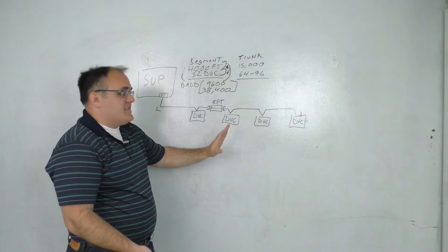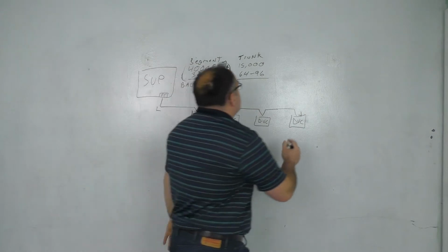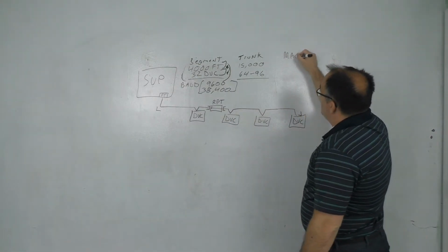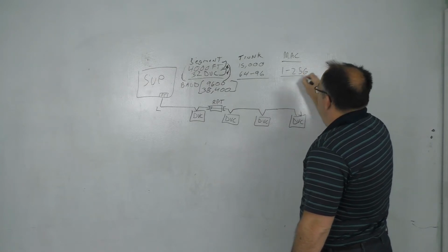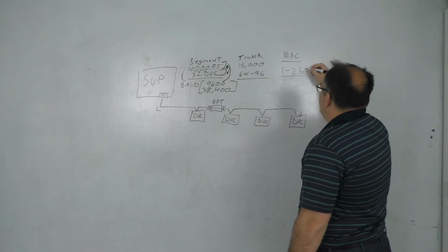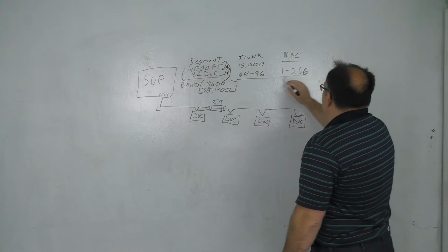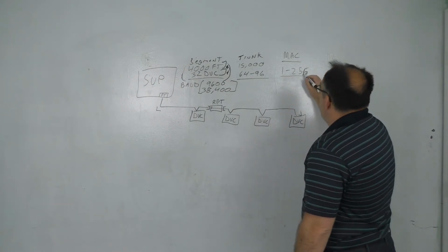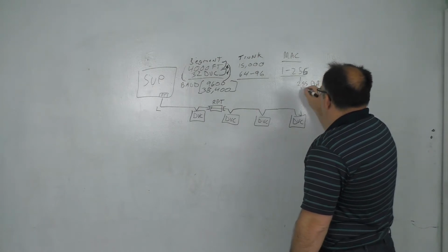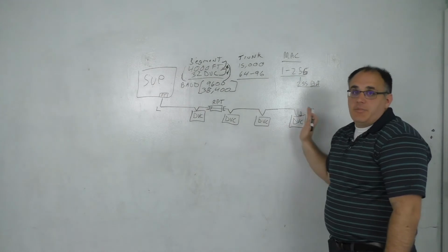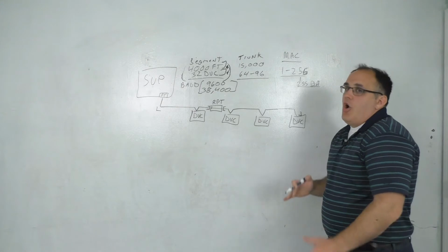Well, the addressing on BACnet is MAC addressing, and it's typically anywhere, let's put addressing over here, between 1 and 255. I always do 256, that's 256 addresses total. And 255 is our broadcast address, which we're just going to call BA. So you should never set a controller to the broadcast address. That is how all your Who-Is and everything gets communicated on the network.